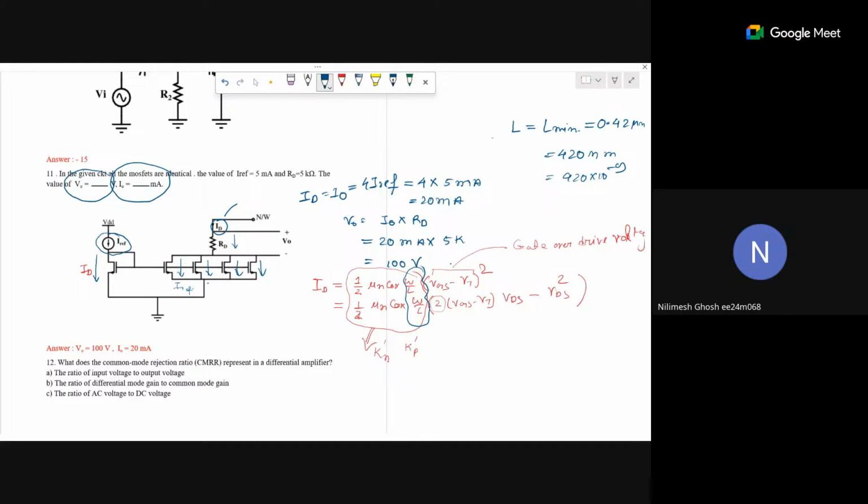So this is how our technology goes. That small is our MOSFET. I'm talking about a practical thing. This 0.42 micrometer is mentioned in the PDK of SkyWater. So just imagine, 420 nanometer is the minimum length. So what is called the minimum length? That minimum length defines that a chip fabrication machine can fabricate a minimum dimension of 420 nanometer.